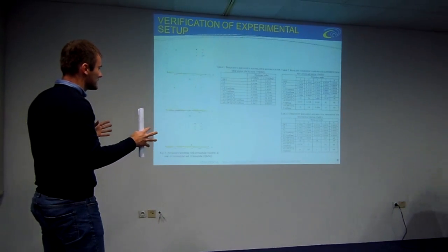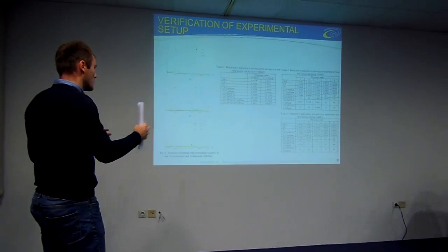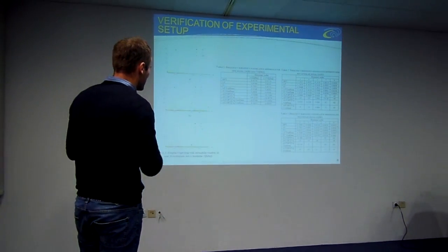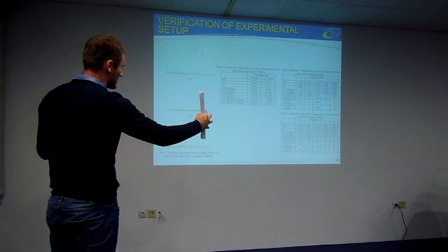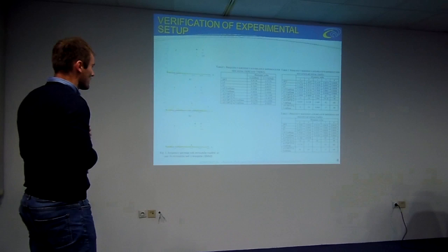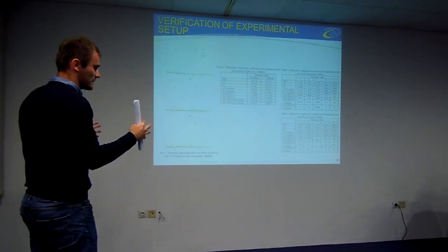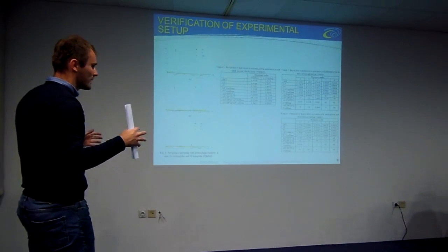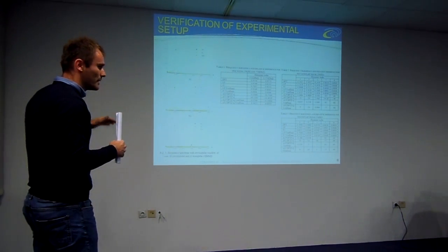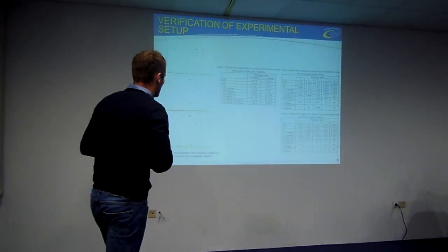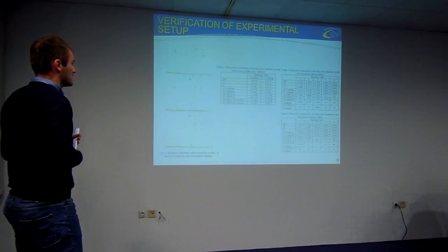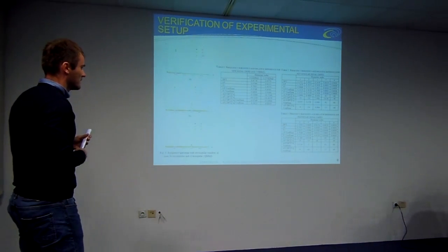But in the automated system, where we use the oscilloscope, we capture a number of periods and points that is not an integer number of periods of that signal, and in that case we have spectrum leakage and error in measurement. In this case, for the 1 kHz signal, the last prime algorithm gives better results.